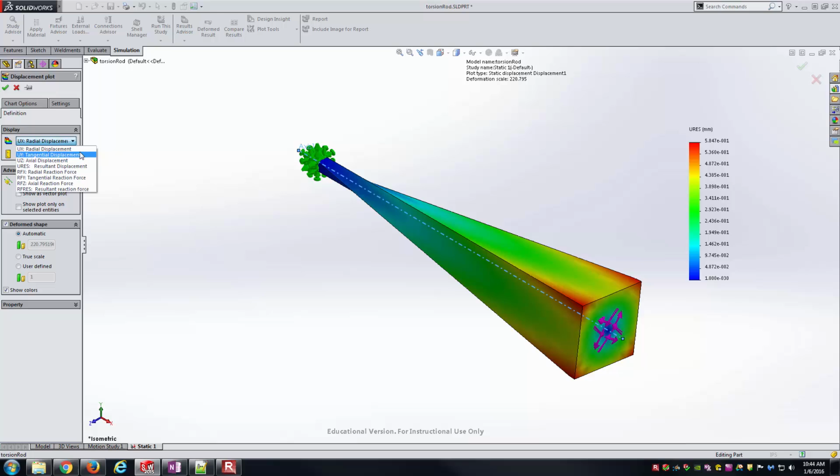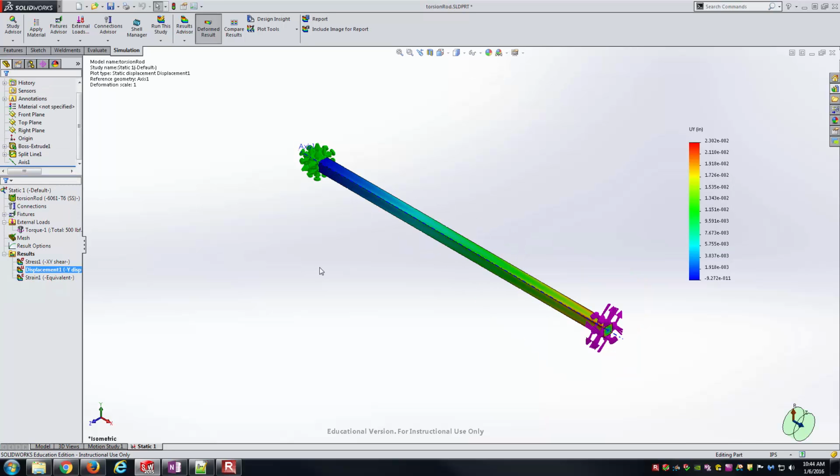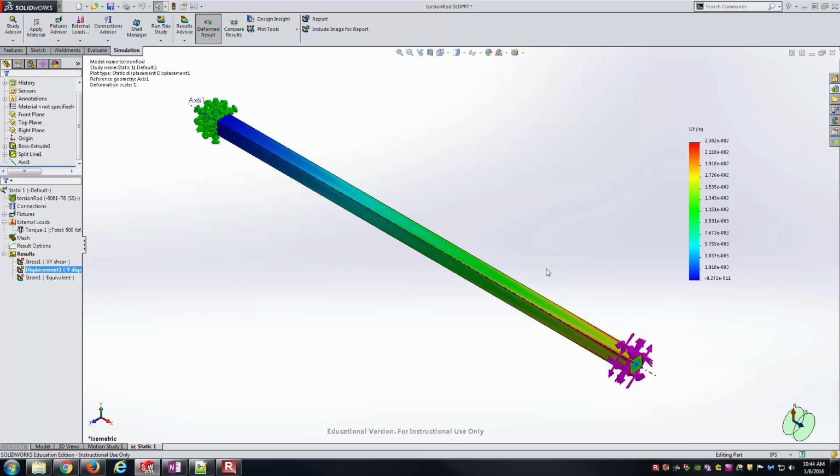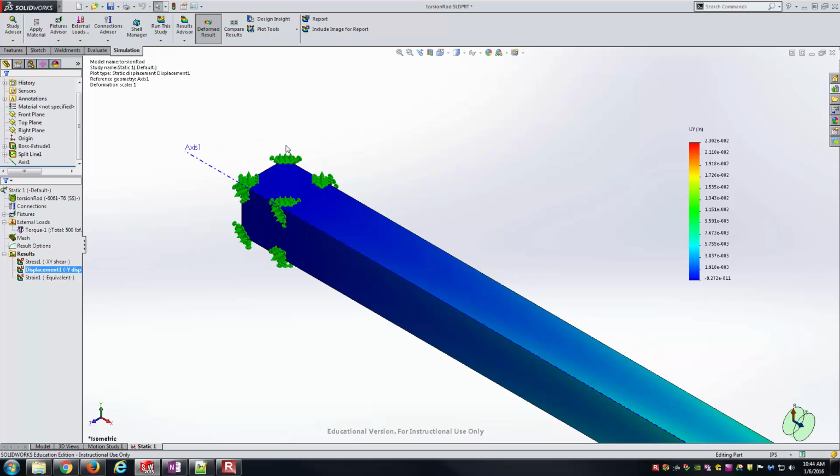And so here we're interested in this tangential displacement. And since we're doing everything in inches, let's keep the length unit consistent as inches there. And again, I'm going to go to true scale. And I'll just accept that plot there. And so you can see the plot just makes sense a little bit. Here you're not going to see very much displacement at all when we get very close to the fixed connection here. That's why it's trending to 0 here.